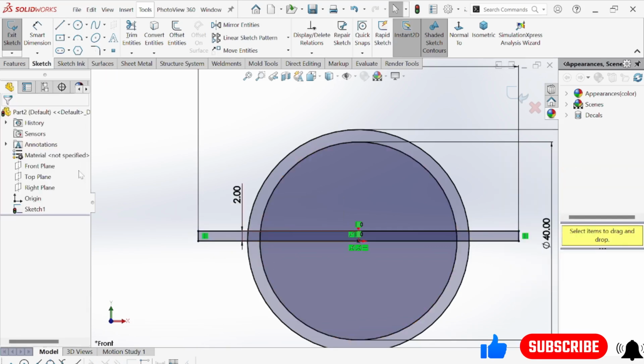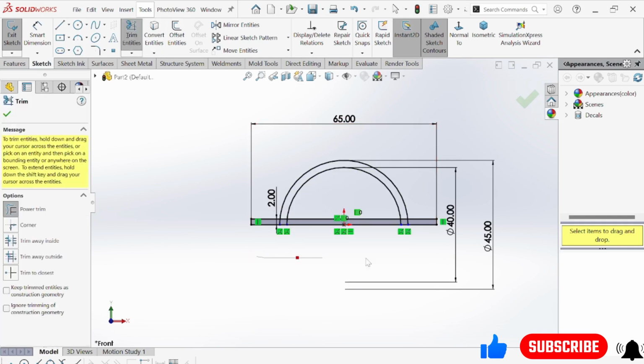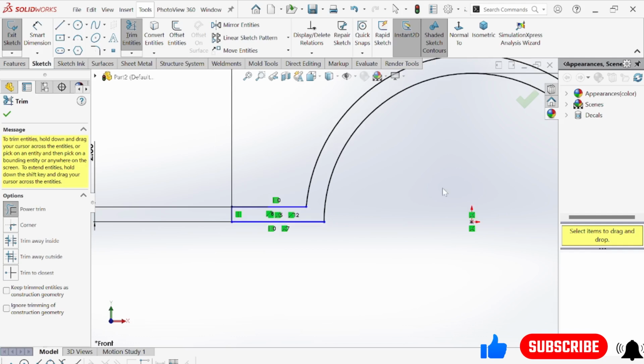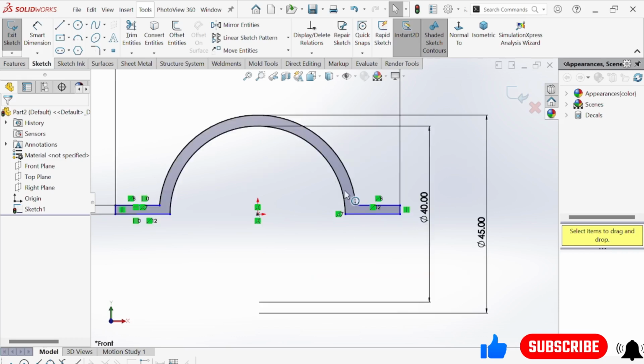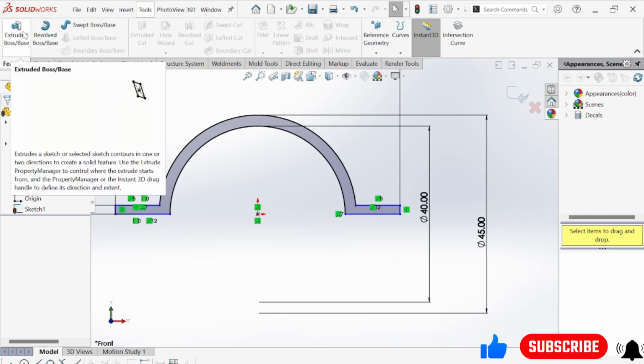Now here you see this one is closed. Now we need to trim the bottom part, because we will use this part as a coupling part. Go to trim entities, simply trim this thing, trim the middle one also, trim these lines, come here, trim this line also, and make this one okay. Now here you see, this is our complete profile. If you want to give any fillet here, then give, or if you don't want, then just leave it. No need to give any fillets.